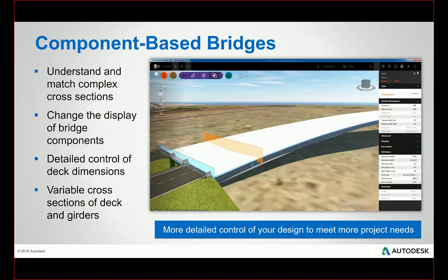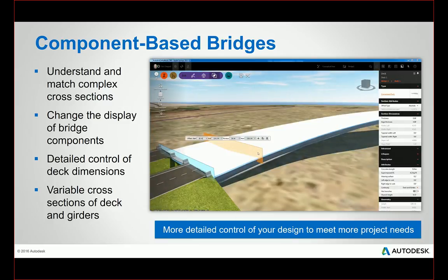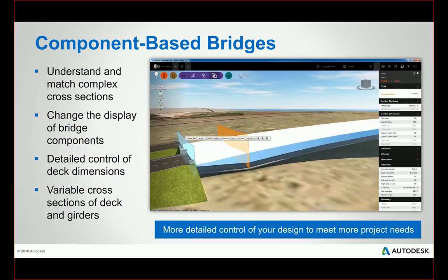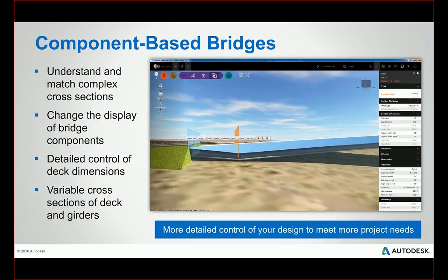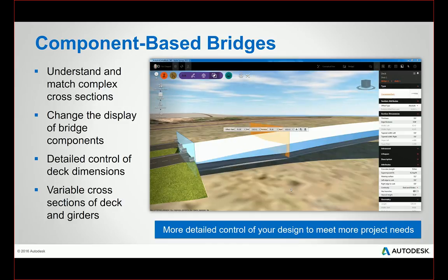So you see here we're going to add that new section, and then over in the asset card for that section we're able to change the values of that cross section. There and the thickness, we can change that now. Again, that varies the thickness from then on. Again, this is dynamic. You can slide that section along and define where you want that to be located, and everything updates within the model.